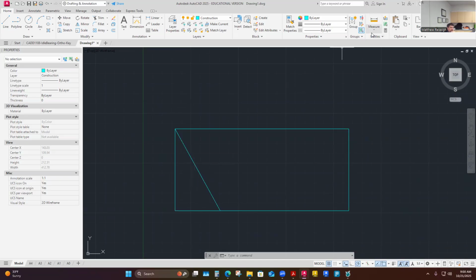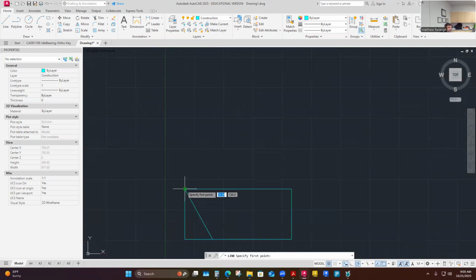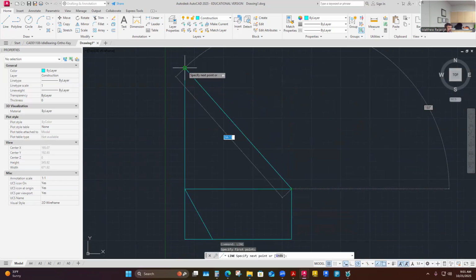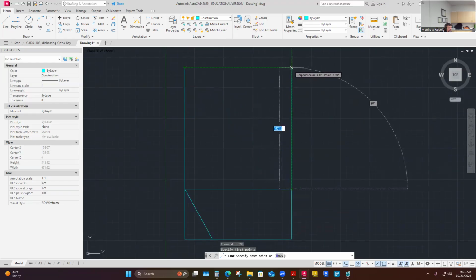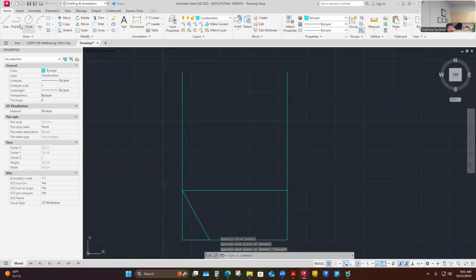And then I never checked what the overall dimension ended up being here, but it's also one that I wasn't explicitly given. 182.5 millimeters. So that's not bad. So maybe I'll just project this up. I'll build a projection plane up here. This is no specific height here. I'm 197 millimeters above this, but I'm just going to give myself a little bit of space.